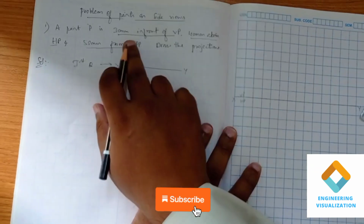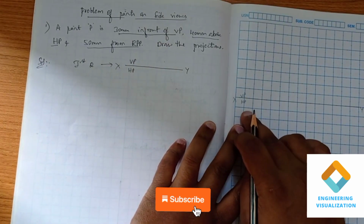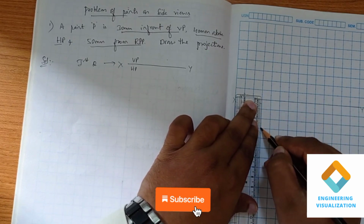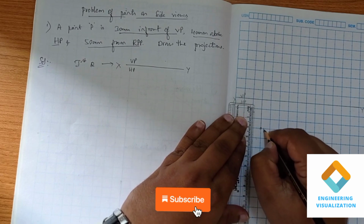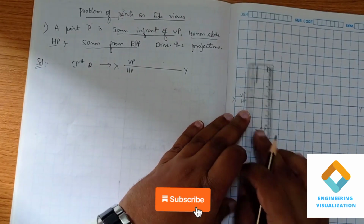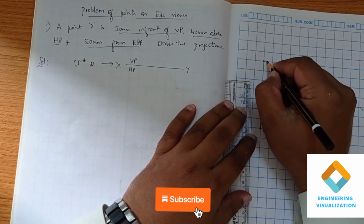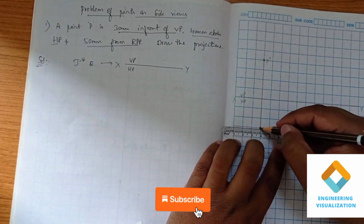Okay. So we know that 30 mm in front of VP means it is the top view. So the top view is drawn in the HP plane. So 30 means 3 boxes, and you put a point. So that is here the top view. Similarly, 40 mm above HP means it is our front view. It is 4 boxes. It is P dash.